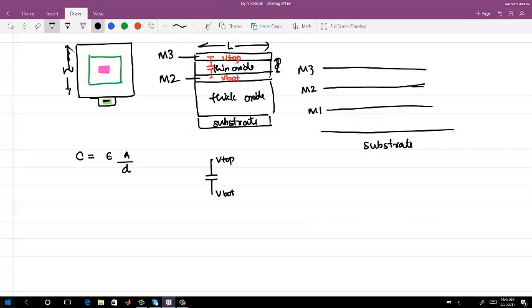And then on that you have a capacitance with respect to substrate. Let me just say C parasitic bottom. And you will also have from the top layer with respect to substrate, CP top. This is C desired. So any capacitance comes with this kind of parasitics.